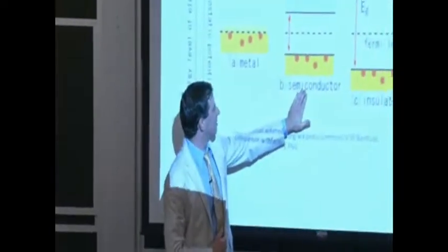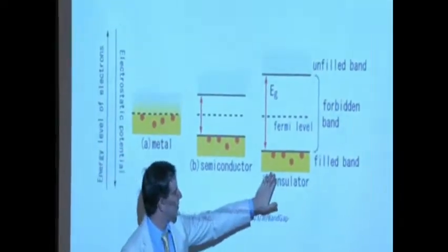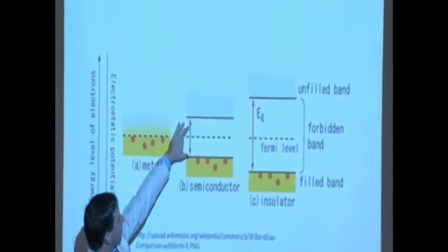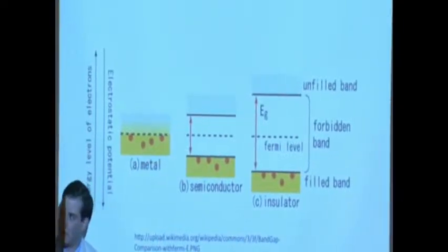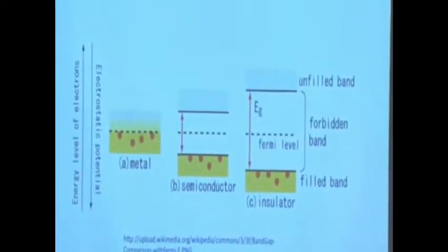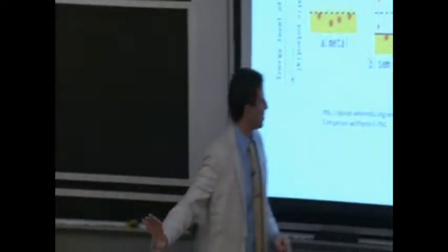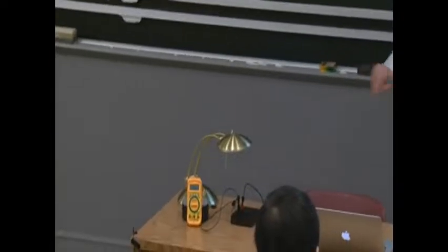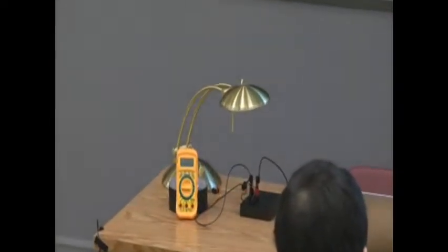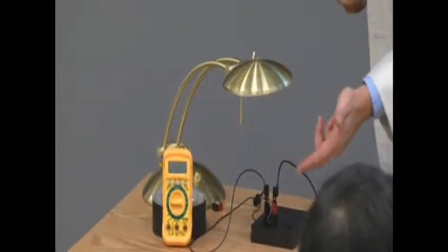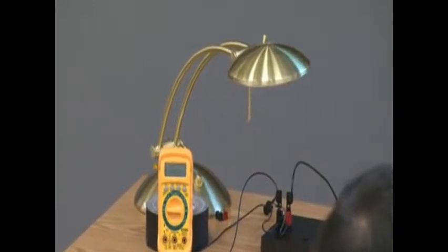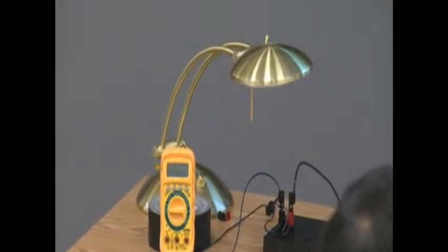Now, a semiconductor material is somewhere between a metal and an insulator here, in that the band gap is now shrinking. The band gap is small enough to interact with light, typically. For example, this little piece of silicon, which I'll show in detail in a minute toward the end of class, doesn't look clear like glass does. It looks opaque. And that's because it's absorbing photons in the visible spectrum, but it's letting some of the infrared photons go through it.